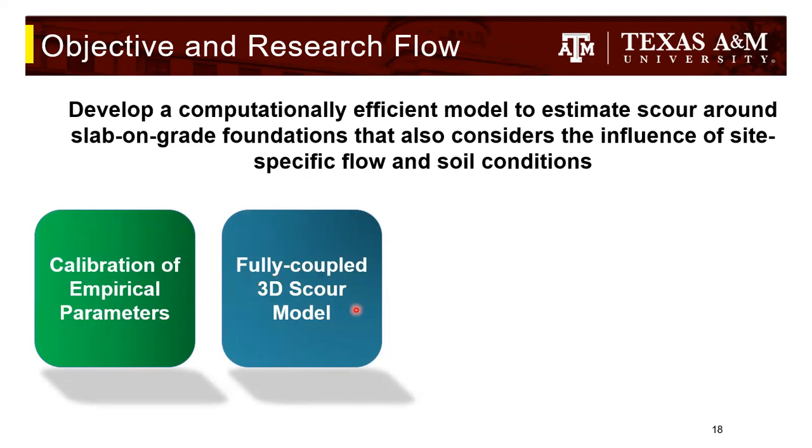And then, parallelly, we determine which are the key parameters which affect the scour. Essentially, the velocity of the flow, the depth of the flood, the duration, again the time to which that foundation is subjected to the flow, as well as the particle sizes, or essentially the type of the soil which is surrounding the foundation.